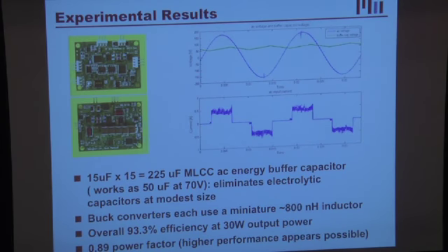If you remember the earlier picture of an LED driver I showed you, the footprint's approximately the same. But instead of having this huge inch-high stack of magnetic components, I've got these two tiny little magnetic components. That comes from A, having topologies that minimize the magnetics, and B, the fact that I'm running roughly 2 orders of magnitude higher in frequency than a conventional design. Okay. Third, I'll point out that here we can see the energy buffering. This is the voltage on the energy buffering capacitor.